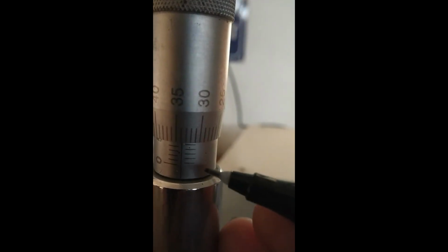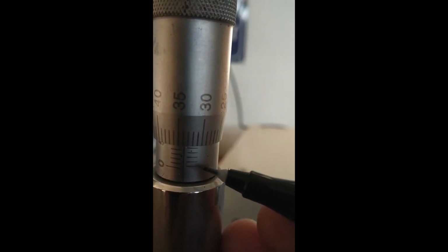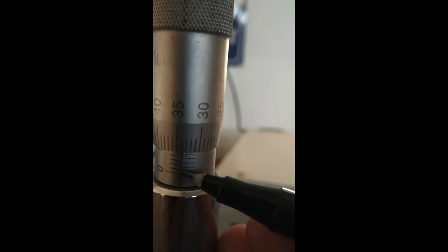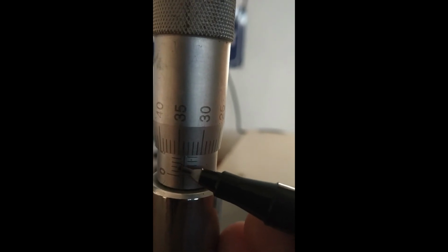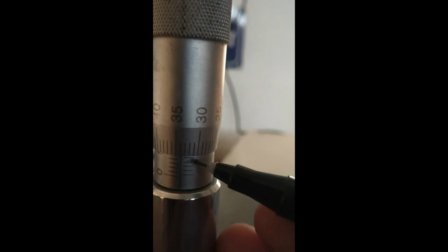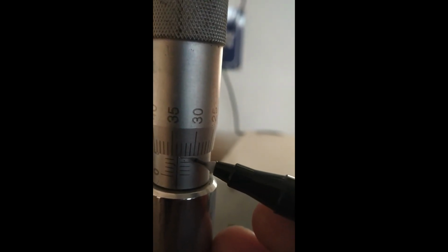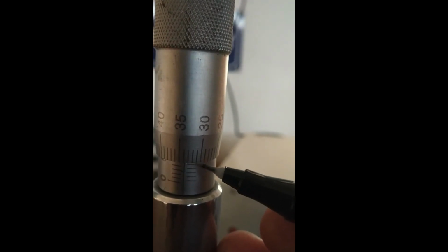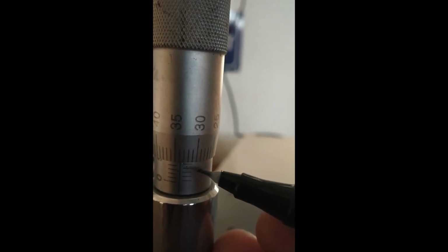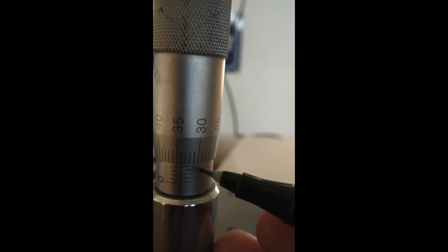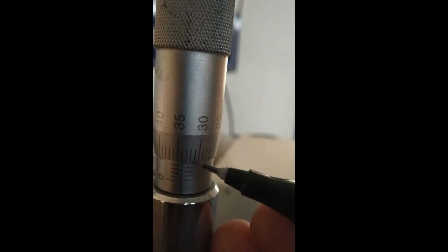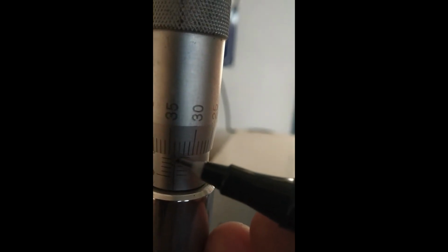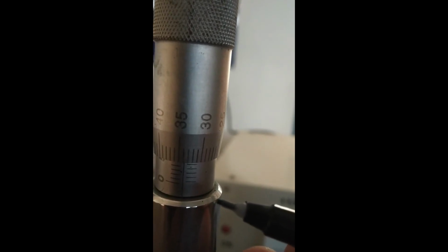This screw is now, if you watch it, this is 0.5, 1.5, 2.5, 3.5, 4.5 is now visible. On this side you can see 0, 1, 2, 3 and 4. 5 is not visible, but 4.5 is visible. So on this side the visible reading is 4.5. On this side the visible reading is 4. So since 4.5 is bigger than 4, the main scale reading is now 4.5 mm. And on the circular scale you can see this is 30, this is 31, this is 32, this is 33, and you can see the reference line is in contact with 34.